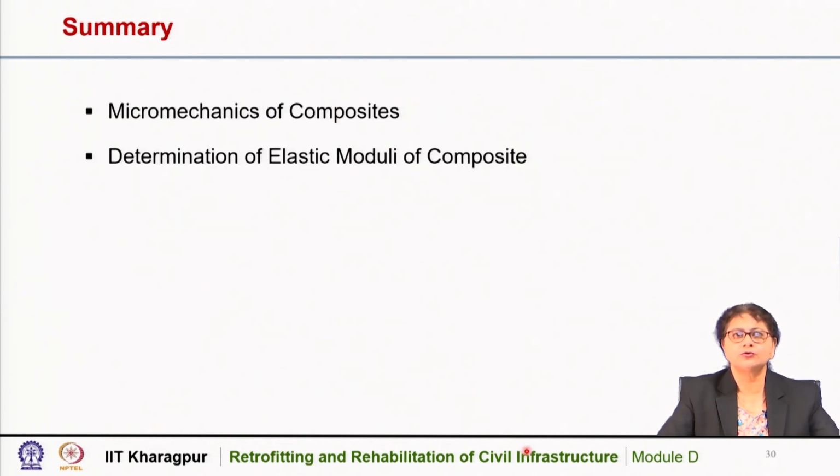So, this shows that the influence of fiber on the composite, the properties of composite can be derived from the volume fraction of the fiber part and the matrix part, and also by knowing their individual properties, by knowing their elastic modulus values, by knowing their Poisson's ratio, we can determine the elastic modulus of the composite in the direction of the fiber or in the transverse direction of the fiber.